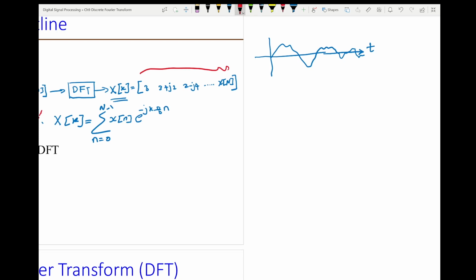According to the sampling theorem, the sampling rate f_s has to be equal to or larger than twice the bandwidth, or twice the highest frequency in the signal. So we have to go by this law, so aliasing will not be a problem in our analysis. And I have a video that explains the sampling theorem. After we decide the sampling rate f_s, we will take these samples.